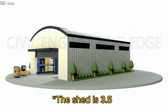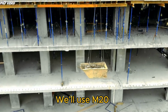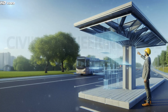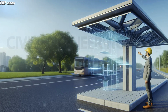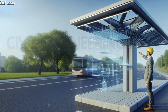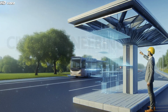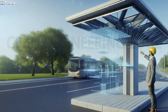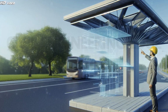Solution: the shed is 3.5 meters wide and 3 meters high. We'll use M20 concrete and Fe415 steel and support a 100 millimeters thick slab with frames at 2.5 meter spacing. Design of the slab: dead load of 100 millimeters slab equals 25 by 100 equals 2,500 Newton per meter squared. Live load equals 1,500 Newton per meter squared. Total equals 4,000 Newton per meter squared. Consider a 1 meter wide strip of the slab.